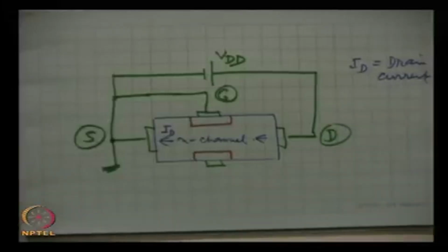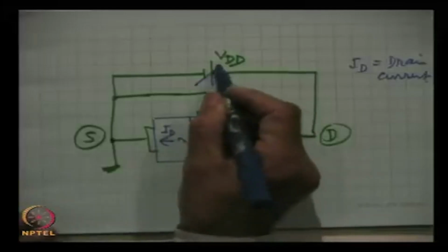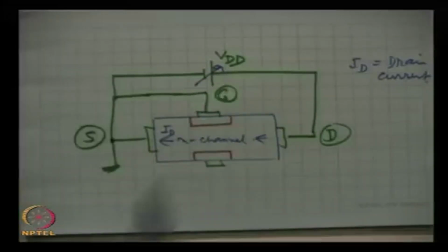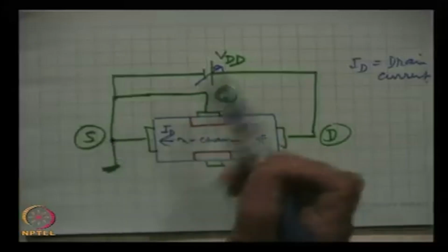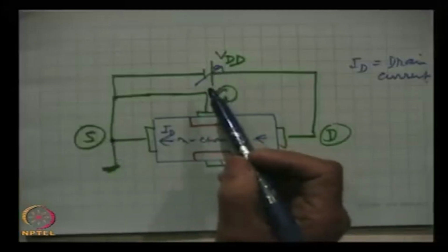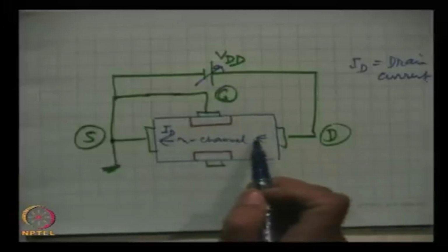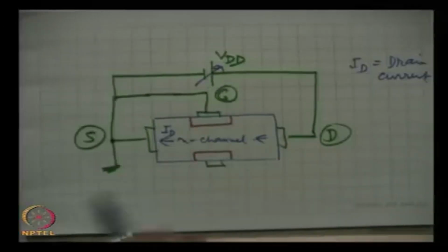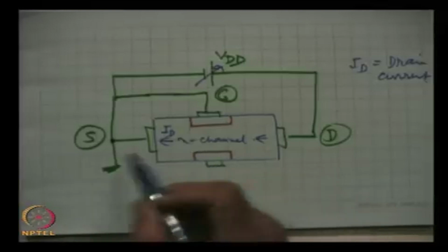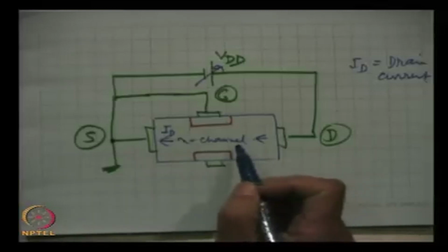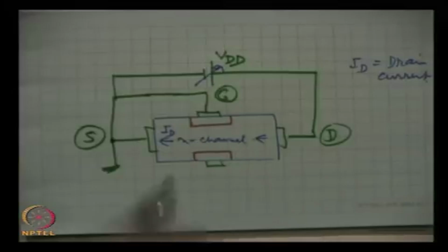which will flow. So, as we start this, let us keep varying the source drain voltage from 0. As soon as we move further, the current will start flowing, and the larger the voltage, the larger will be the current. Now, what happens to the depletion region?